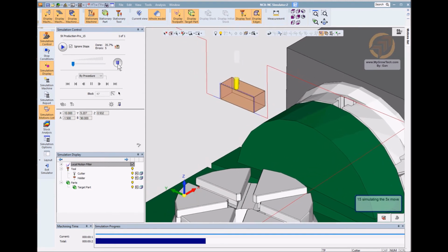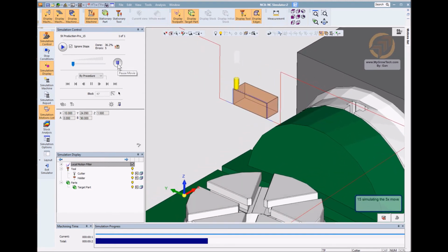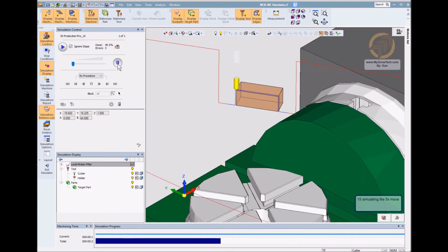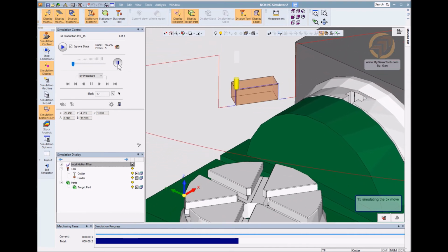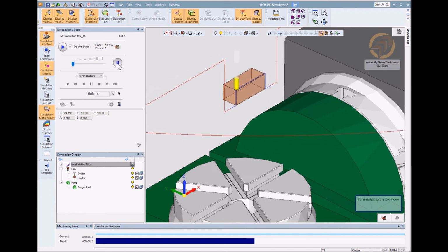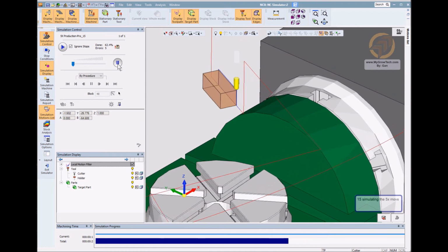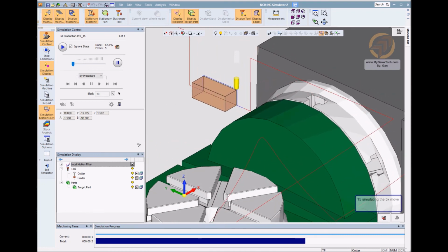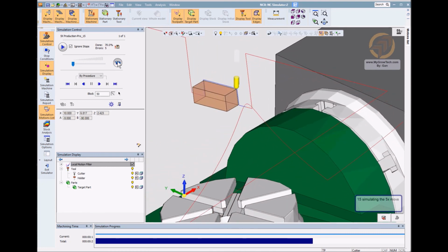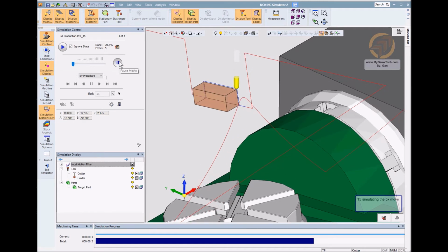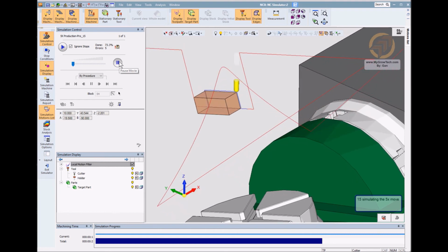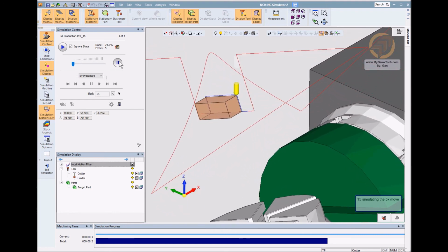Right, and because of this, Cimatron will automatically apply a swap. A tool swap. This is called in place tool swap. Okay, turn the rotary table 180 and then continue, so that all the A axis angles are always negative.